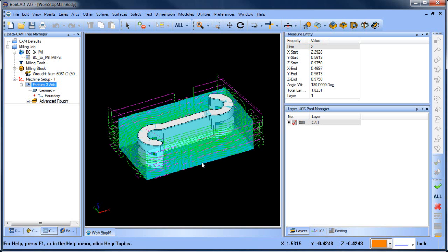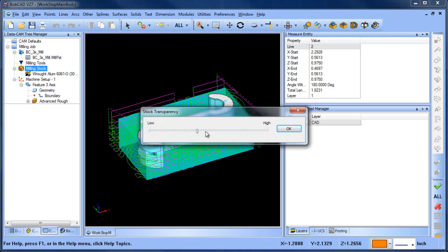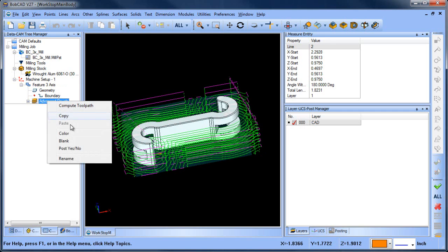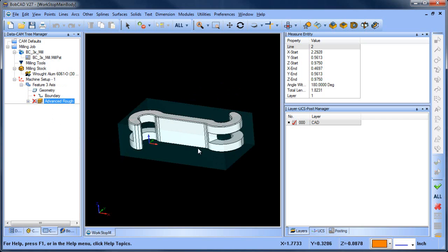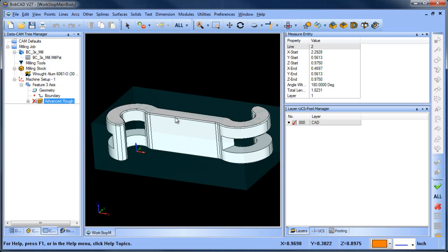The next thing we want to do is finish profile outside 2 passes. So let me go ahead and blank this out. So part of what we got going on here, and let me blank this too, is when we're doing 3D machining, it's really simple. We can pick this up. When we go to do 2D machining, we can use surface edges. Sometimes you can get away with this, but we have this chamfer here, and that's kind of making this a little problematic.